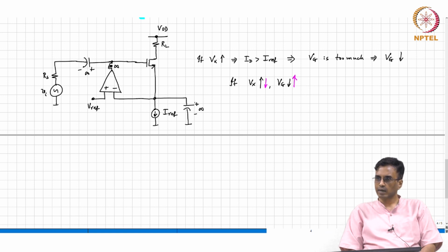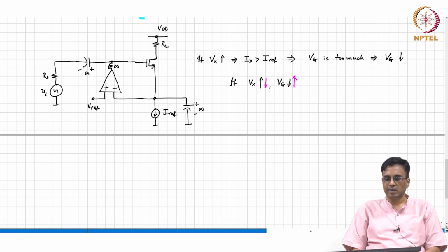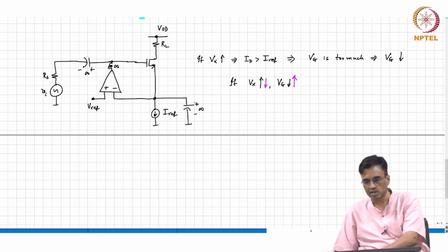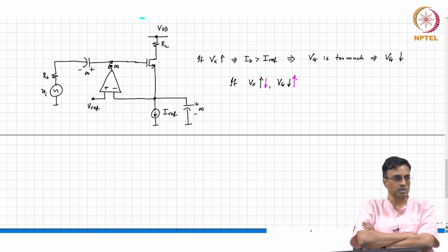Does that make sense? Okay. And for each of these amplifiers, you can now go and figure out what the swing limits are, right. It is the same old approach. You find the total potential at the gate, the total potential at the drain, the total potential at the source.